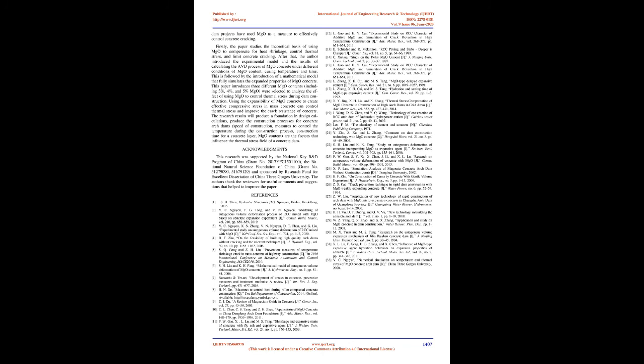Firstly, the paper studies the theoretical basis of using MgO to compensate for heat shrinkage, control thermal stress, and limit concrete cracking. After that, the author introduced the experimental model and the results of calculating the AVD process of MgO concrete under different conditions of MgO content, curing temperature, and time. This is followed by the introduction of a mathematical model that fully simulates the expanded properties of MgO concrete.